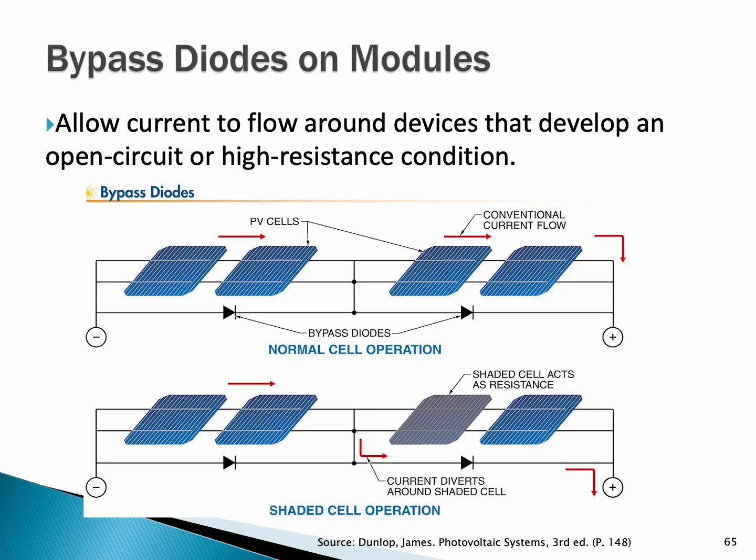When we have a shading, that's resistance. So in the first cell group, things are operating normal, running through the grid, hits the resistance, takes this alternate route. It can't go backwards because this is a blocking diode, it can only go one direction. So current will take the path of least resistance and go through the bypass diode and continue on through the system.